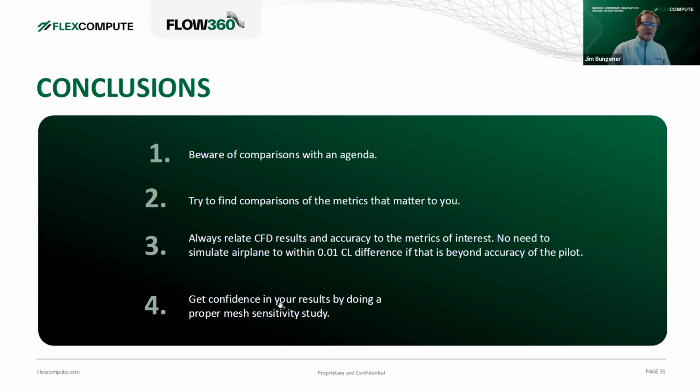And get confidence in your results by doing a proper mesh sensitivity study. You'll learn a lot about the flow features, where the vortices are, which are the interesting areas of the flow field, and get answers about how much you can rely on the CFD simulations, where the CFD simulations behave well, where they are more difficult to run. So there's always a lot of information that can be garnered from a proper mesh sensitivity study.